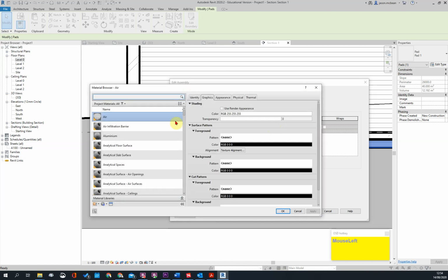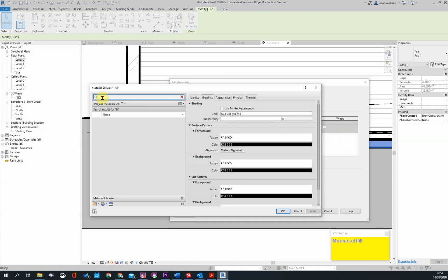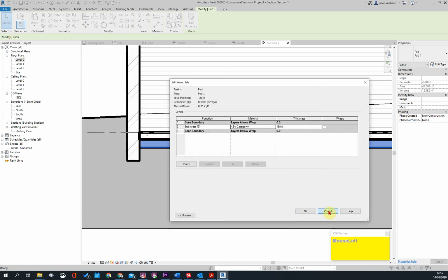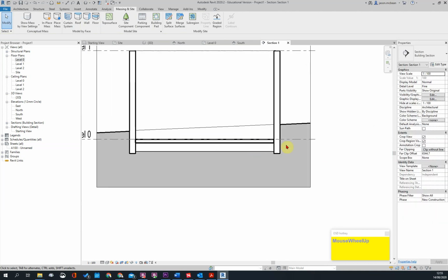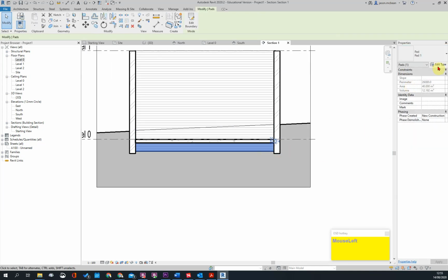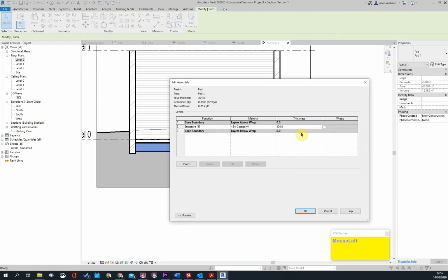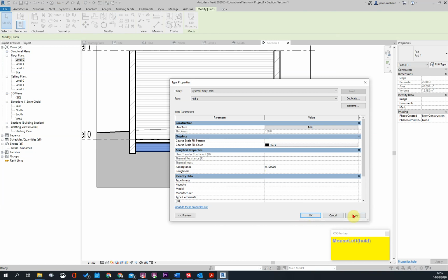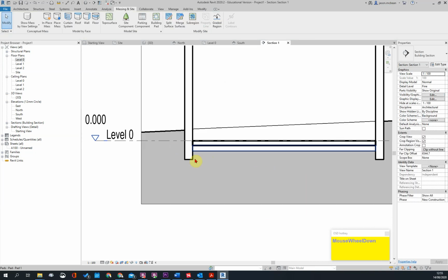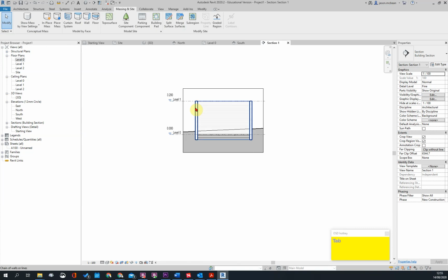I think I have got the full layer ready. I hope I have. Okay, I don't. I'll have to make that material, so I'll leave it out for now. Anyway, let me just change that. It must be 150. 150. Okay. Apply. Okay. Anyway, so that's your surface bed, and I'm going to select or tab all the walls.